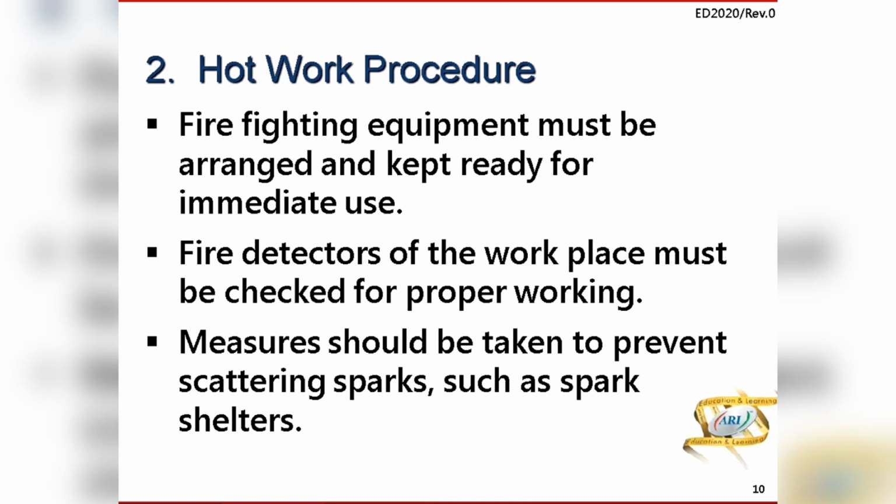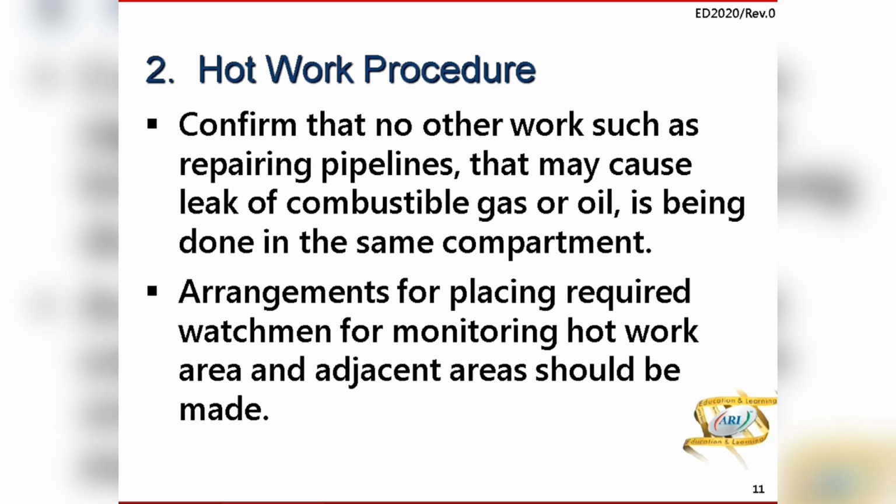Firefighting equipment must be arranged and kept ready for use. Hoses to be pressurized and kept ready for use. Fire detectors in this space should be properly working. Measures should be taken to prevent scattering of sparks, so spark shelters should be there. Confirm that no other work is being carried out, because that may cause a leak of combustible gas or oil.